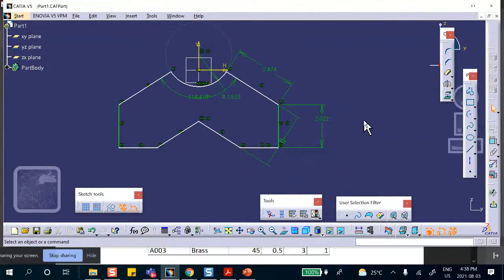Now, you don't have to do it like that, but I'm gonna tell you what I have in mind, and that is, notice that it says this edge must be equal to that edge. So if this is W, this is also W. There's two ways to do that. One is to make this dimension this and say this dimension equal to that dimension.